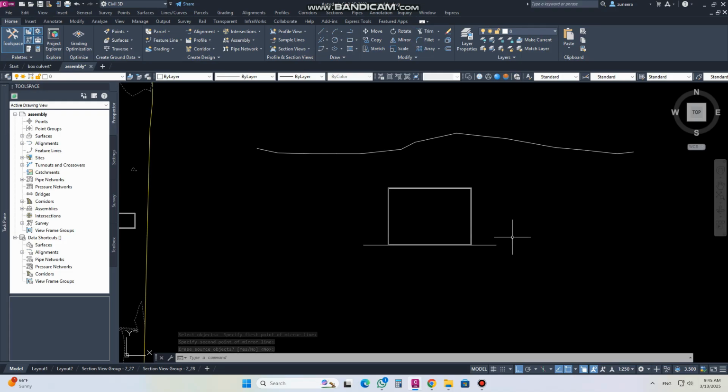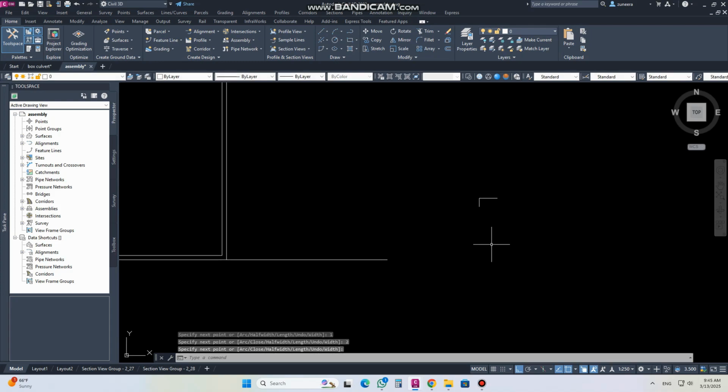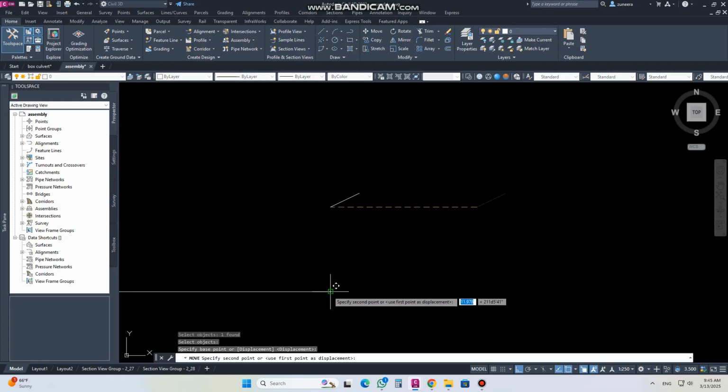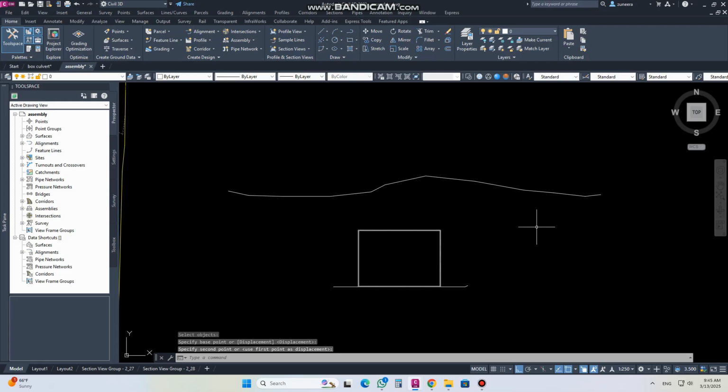There is a vertical side and then a slope. Let's say the side slope is 1:2. Mostly the side slopes are 1:1 or 1:2, as you will take from your construction drawing or from your shop drawing. So I will just practice on it. So let's say this is the side slope. In this we will excavate to the natural ground.